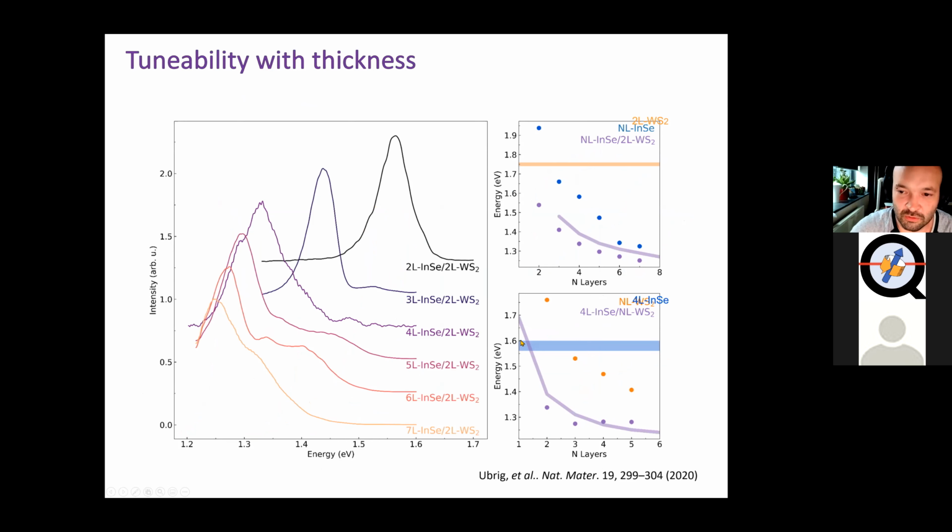And that can be tuned in a broad range using the thickness of the materials, because you now have two materials to basically pick and control the emission. And we measured it down to about 1.2 eV, but if you pick the right TMD, you can actually go to that sweet telecom 0.9, 0.8 eV range to achieve that emission.